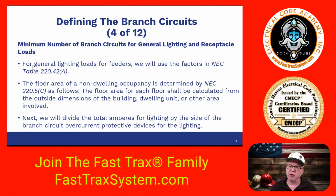All right, let's start out with the general lighting. Again, we're doing commercial, not residential. For the general lighting loads for the feeder, we will use the factors in 220.42(A). Let's go to the NEC and look at that. By the way, we're in the 2023 edition of the NEC.